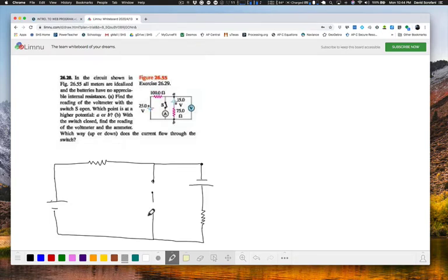I don't love the way it's drawn in the diagram. It almost looks like it's another branch of the circuit, which of course it is, but having the huge resistance that voltmeters actually have, very little current ever traverses that path. So I'm actually going to draw it a bit differently. I'm going to put the voltmeter like this, and then just connect like so. And by doing that and using a different color, I hope I'm giving you the impression that it's not really to be thought of as an alternative path for current flow. You don't have to consider this as another branch of the circuit, because that voltmeter has a huge resistance inside of it.